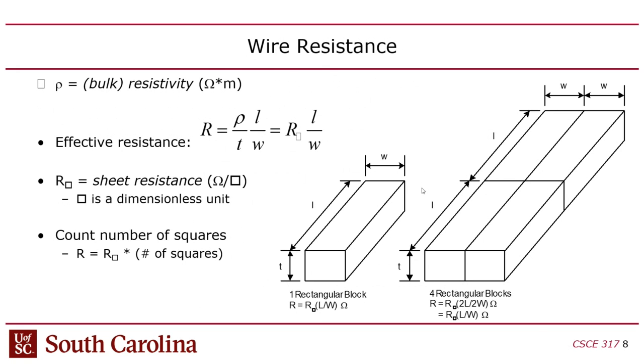Unfortunately, copper has some horrible side effects. Copper atoms will actually leach into the silicon. So in order to do copper wires, they had to come up with this way of insulating them with a layer of silicon around them, or polysilicon around them. Also, copper has this thing called cupping, where you can't make the surface of the copper flat because it kind of dips in. So there's a bunch of challenges related to that, but most of those have been worked out, and now chips use copper for their wires.